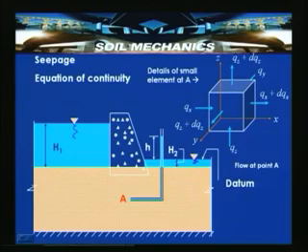So, in the x, y and z directions, we have seen the flow entering the element and the flow coming out of it. Now, let us apply these conditions along with the various forms of Darcy's law and derive. Let us consider how we can compute the flows entering the soil prism under consideration, which has dimensions dx, dy, dz.